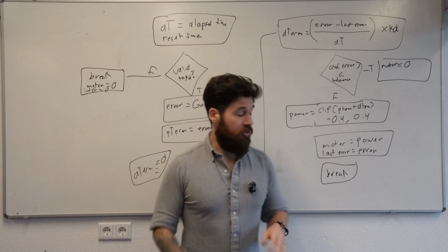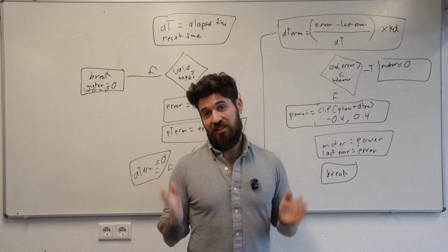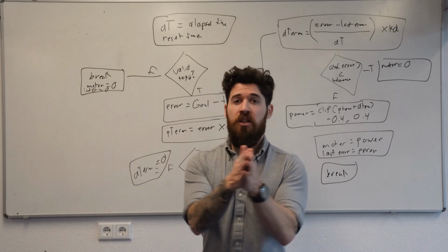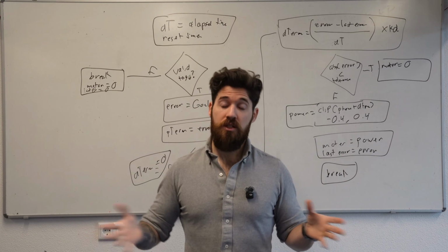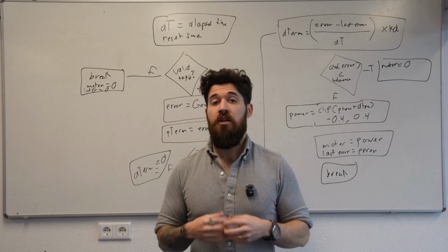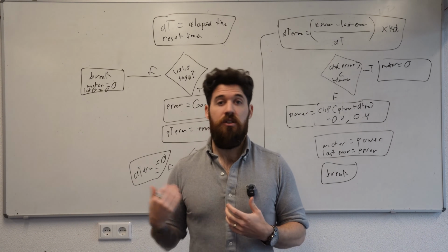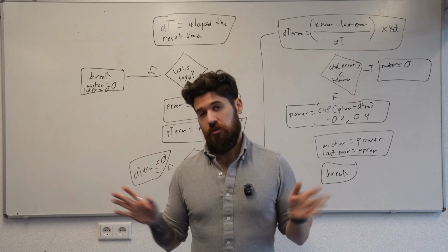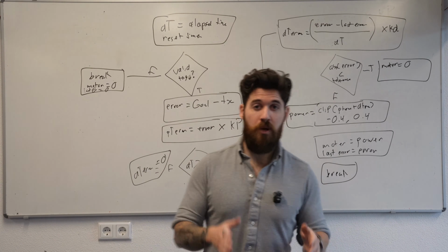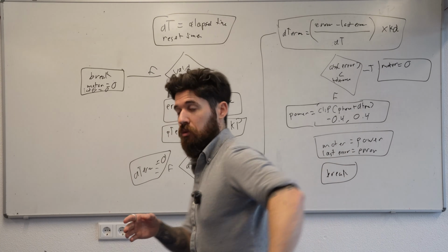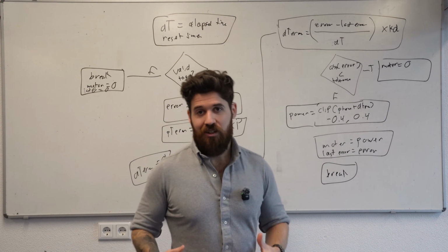Now, one final caveat I forgot to mention. Right here, in this current setup, there are currently no safeties on that system. So it's entirely possible that we could spin around a full 360 degrees. That works great if you have something like a slip ring for your system, where if you have any electronics on your turret, it's able to rotate around and you can transfer power through that and there's no issues. If you don't have a slip ring on your system, you can probably tell the problem that's going to pop up now. If you have a wire hanging on your cable as you rotate around, you're eventually going to get to a point where your wire is actually going to get caught.